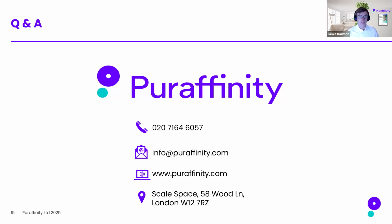Typically, the main contaminants we recommend pre-treatment for would be TSS, as with most products, just to reduce the amount of solids going into our vessels, reduce the backwash frequency, and TOC to less than 10 ppm, ideally. But you saw there we've got some pilots again where we're up at 15 ppm, and we didn't see too much detrimental impact of those concentrations.